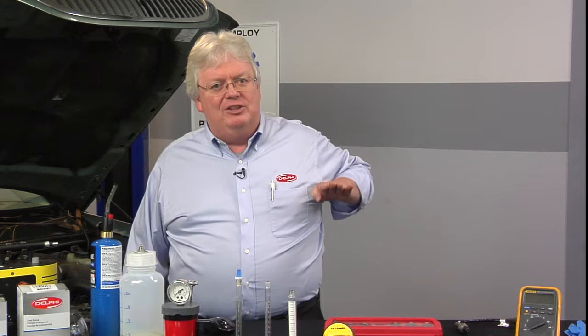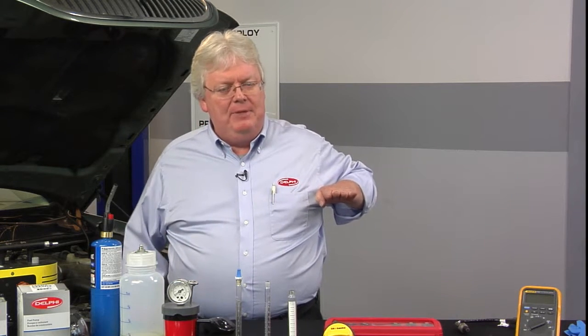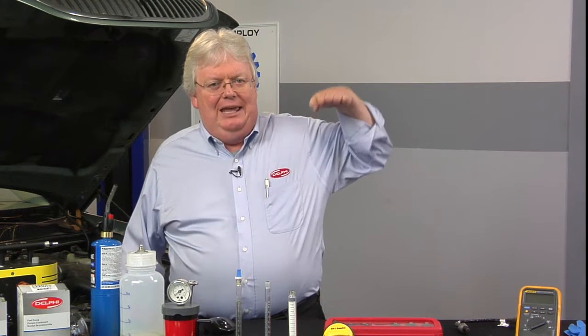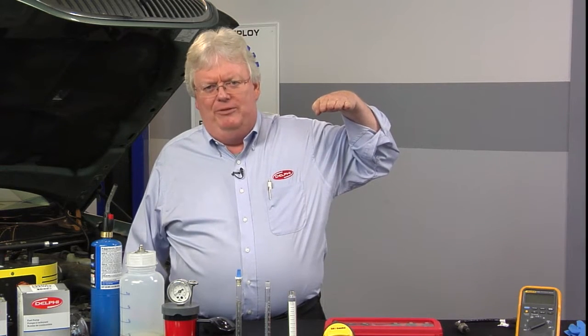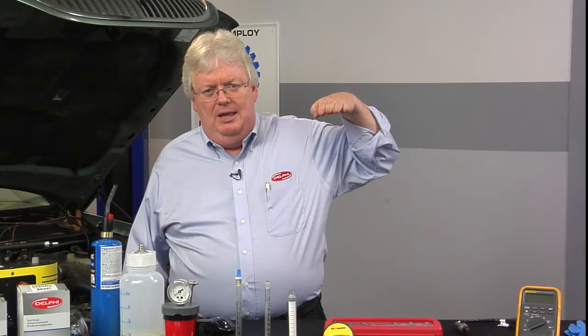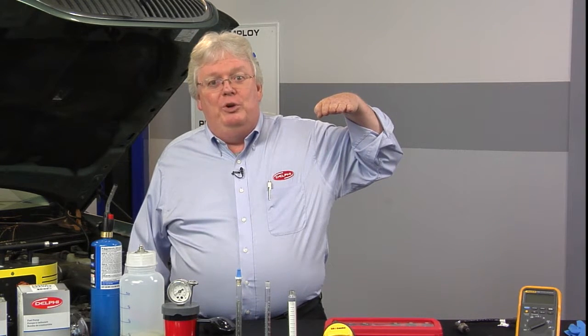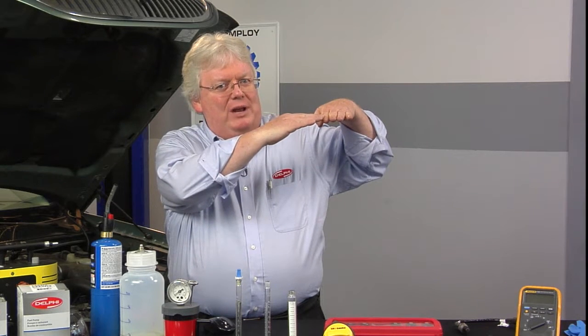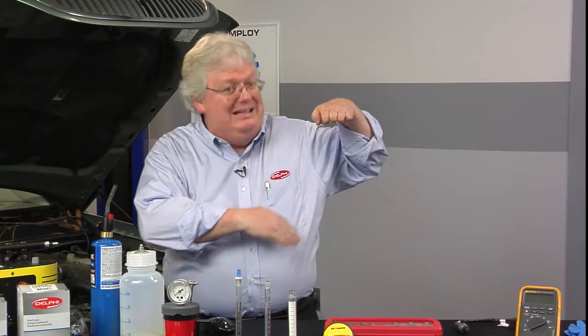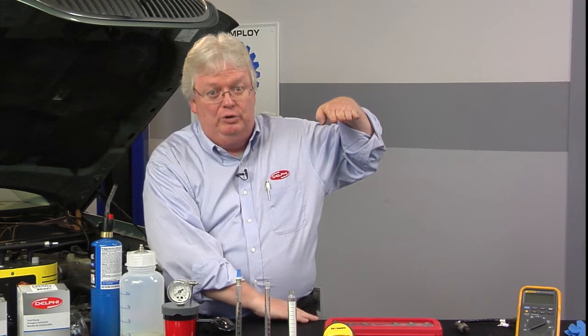But if it goes higher than stoich, higher than my label here, if it goes 16, 17, 18 to 1, that's a leaner mixture. So we need to add more fuel to compensate if it goes lean. Normally an O2 sensor, when you're lean, is going to be a low voltage, high air fuel ratio, higher than 14.7, 16 to 1, for example, low O2 voltage.